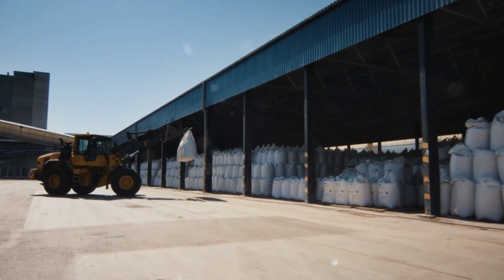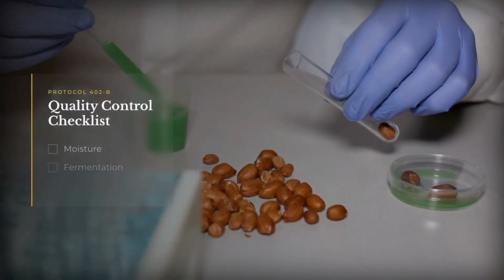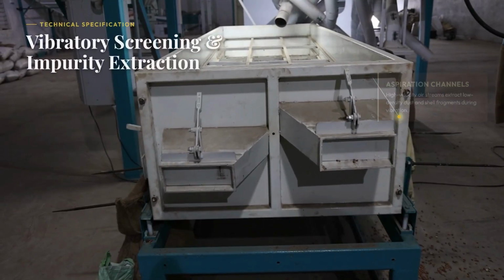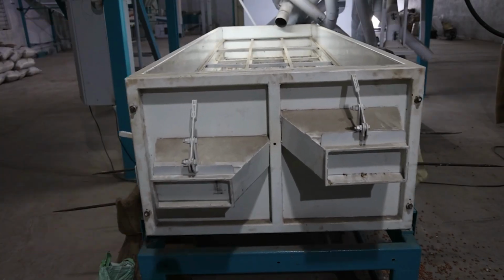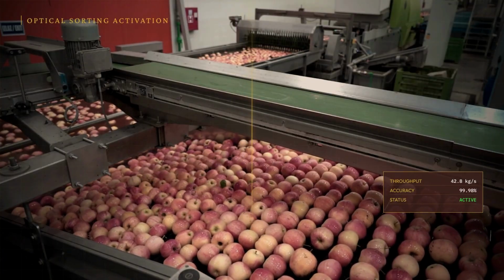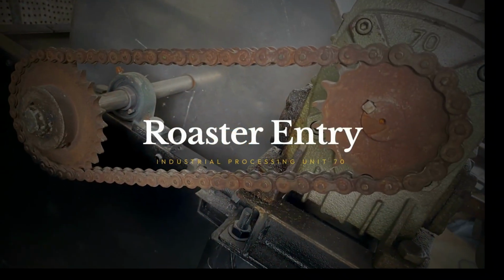The process begins with fermented and dried cocoa beans. Before production, samples are checked for moisture, fermentation quality, bean size, mold, insects, and foreign material. Vibrating screens separate oversized debris, magnets capture metal fragments, and aspiration systems remove dust and light shells. Optical sorters may reject discolored or damaged beans using high-speed cameras and compressed air jets. Uniformity is critical because beans of different sizes absorb heat at different rates. If the feed is inconsistent, some beans remain under-roasted while others burn.